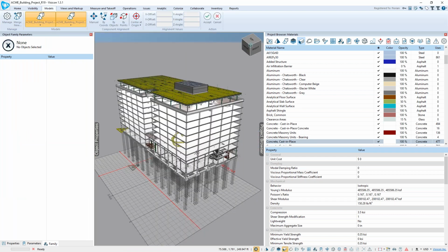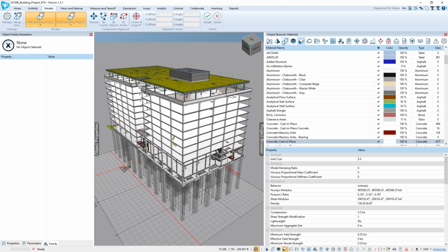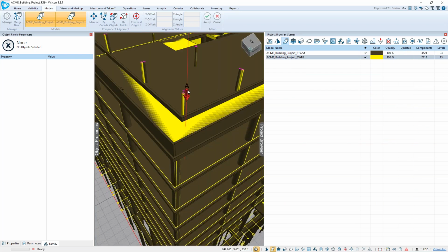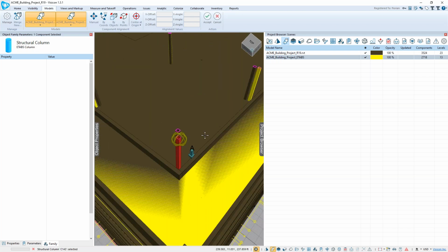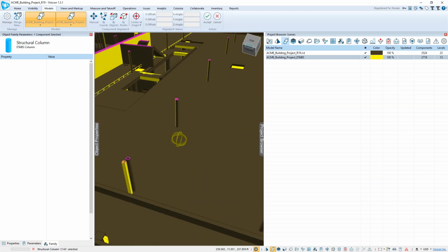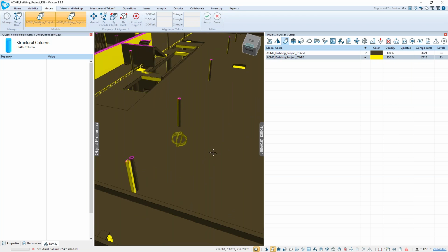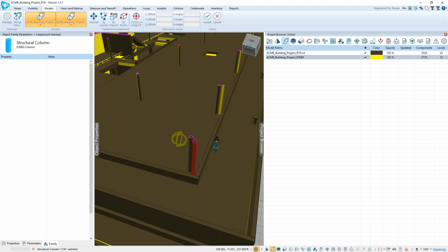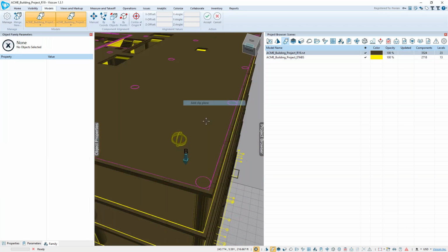If we go to the differential color coding based on model type, I can now add a quick clip plane. And as we go through, I can observe that, wait a minute, there's a discrepancy in my column placement. So here I'm off on my steel columns. So this interior column is well aligned. These exterior columns are off. If I come in and add another clip plane, here I can see, however, at this lower level, my columns are aligned.